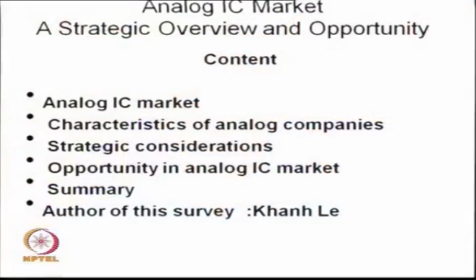The basic analog memory is the storage of a constant current. So one current is 1 bit, the other current is the other bit. I can have a current mirror which has a constant current generator somewhere which stores that current. So that is what, and we use the same structure as the EEPROM structure to do this, from floating gate kind of memories. So this is a new memory which probably is going to be used very soon, new flash.